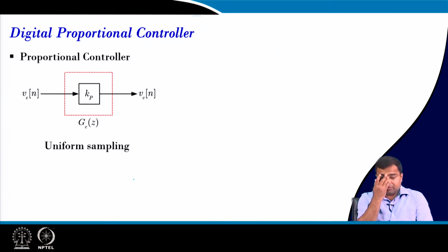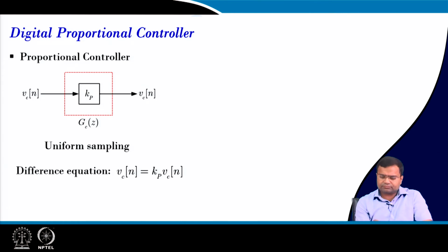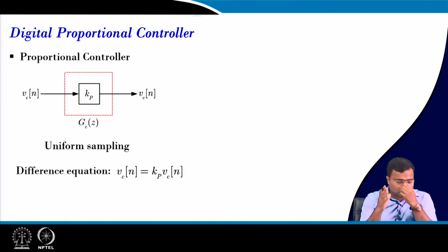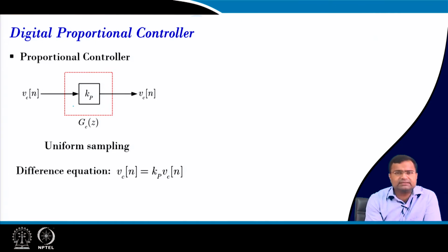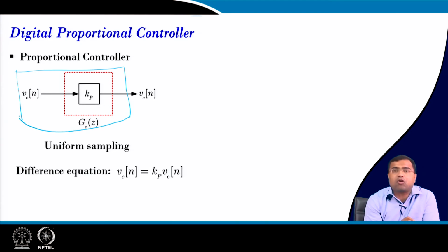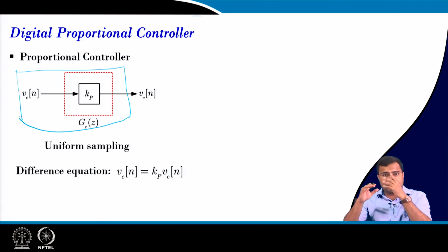Now, in a proportional controller, you can make this multiplication with respect to clock. This proportional gain is just a multiplier, but we may have to use this whole operation in synchronism with a clock, because when you talk about Verilog HDL, we want to compute Kp, Ki, Kd in synchronism with a clock.